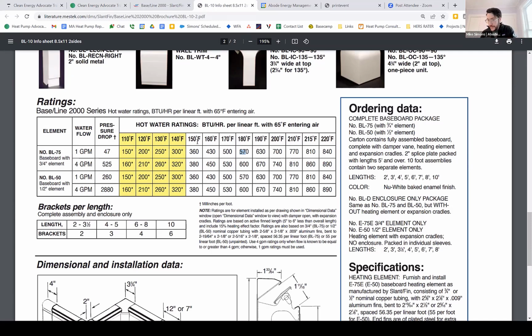So it's not that you can't do it, it's that you need to look at each room, figure out what the actual heat load is, and then size down the BTUs based off of the water temperature that's going in, and think: is this safe or is this risky, and how low can I set the air to water heat pump?